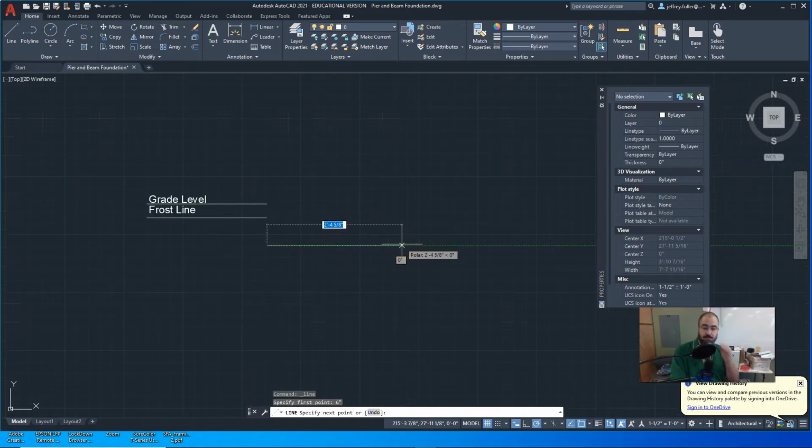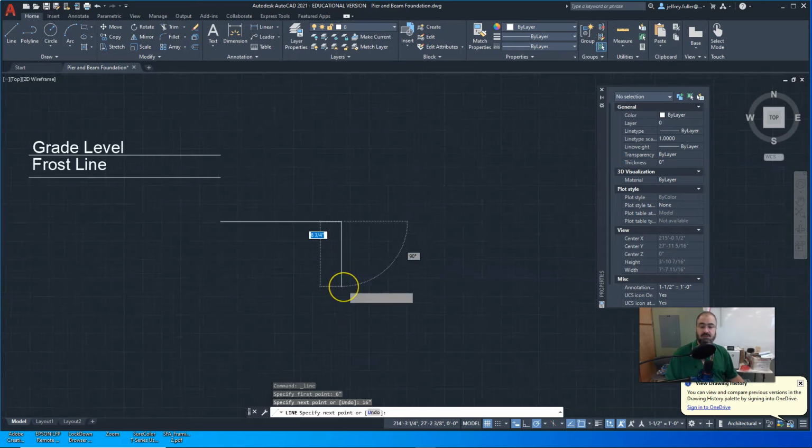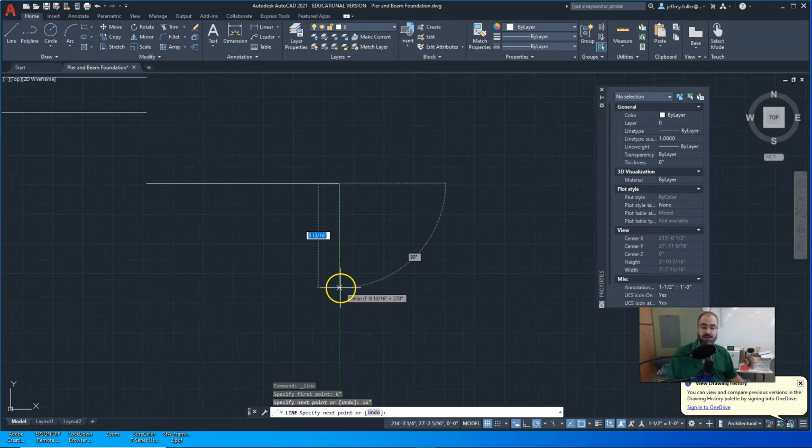And the footing size will be determined by a structural engineer, but we're just going to say that this one's going to be 16 inches, okay, and that is going to be something I'm going to have you jot down a little bit later so you'll understand why it is 16 inches, okay? And then the depth or the height of it is going to be 12 inches.